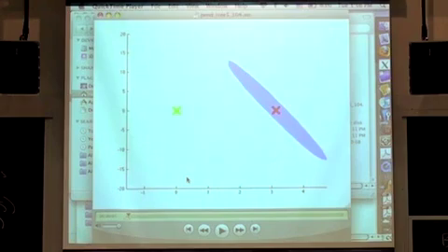There were ellipsoids around the fixed point. I do a sums of squares optimization to verify that this function is negative definite, which involves a higher order polynomial expansion of the dynamics in this form. And I try to find the biggest contour for which that system is still negative definite.